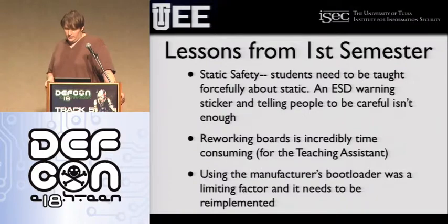A lot of things we learned the first time around when we taught this is, again, static safety. Students don't understand what that is, and a lot of people don't understand what that is. So we tried to enforce that by putting everything in a static bag and telling them that these things are fragile and you should handle it by the edges and so on. And the reason we want to be careful about static is I spent about 40 hours replacing dead chips on these boards last time around, which was not fun. And since lead is poisonous, I really don't like replacing chips.